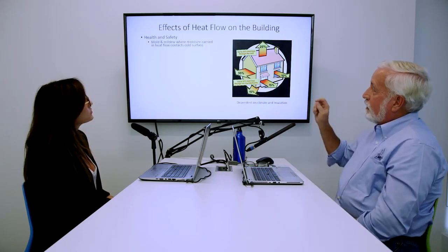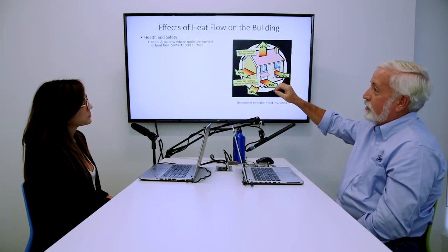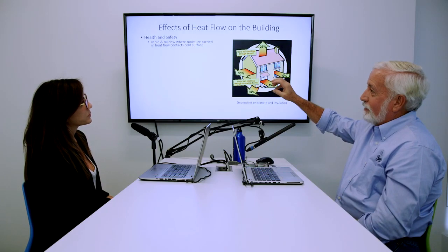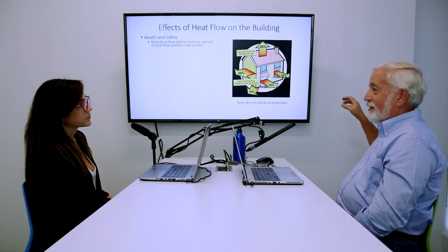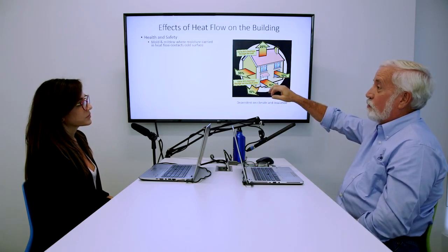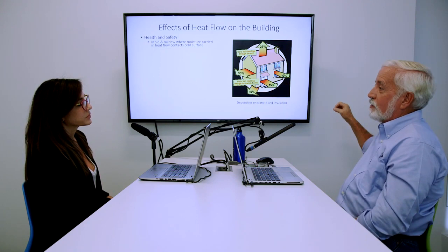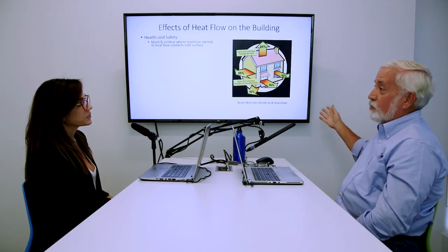Well, heat also transports moisture. So warm moist air moving to the outside will also transport moisture through the insulation and against the cold surfaces.